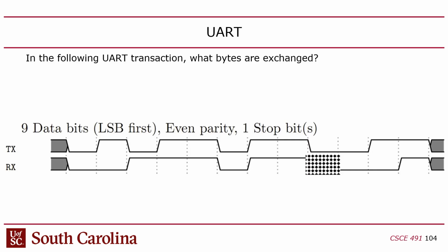Now you might say, wait a minute. Why would you pay the overhead of a start, stop, and parity for each individual data word? Why not support multiple transactions like SPI does, where you have one start and then you can send multiple bytes, and then your parity and then the stop? Why not create a packet format? Well, they don't. It doesn't work that way. There's no way to do streaming, and no way to encapsulate multiple words within one frame or one transaction with UART.